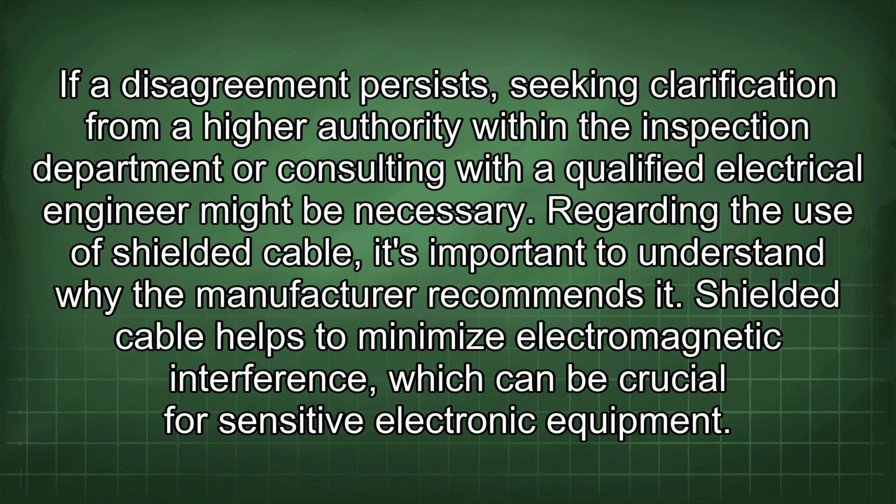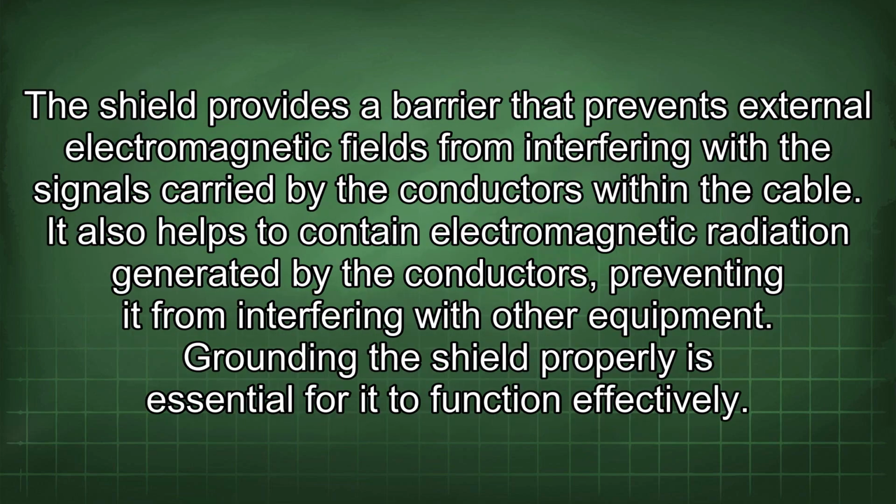Regarding the use of shielded cable, it's important to understand why the manufacturer recommends it. Shielded cable helps to minimize electromagnetic interference, which can be crucial for sensitive electronic equipment. The shield provides a barrier that prevents external electromagnetic fields from interfering with the signals carried by the conductors within the cable. It also helps to contain electromagnetic radiation generated by the conductors, preventing it from interfering with other equipment.